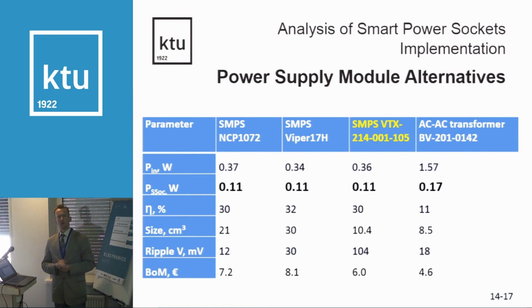And indeed, it is achievable with off-the-shelf components to achieve quite low power for the operation of this power socket itself. It was mainly in a listening mode of the transceiver, not in a sleep mode, and it was quite below the standby requirements of the EU eco-design directives.